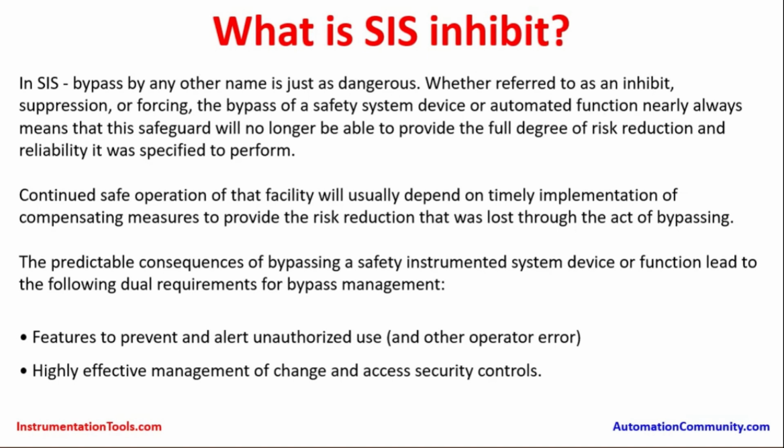So there will be a request coming to the shift manager. The shift manager will assign it to the respective maintenance personnel or instrumentation personnel who is in charge of that plant area, and they will review it and see the other process conditions are okay to do the bypass and then do the bypass. Again, when everything is getting normalized, he has to close it in the system, which goes back to the shift manager to close at his end, so that the complete loop is getting completed.